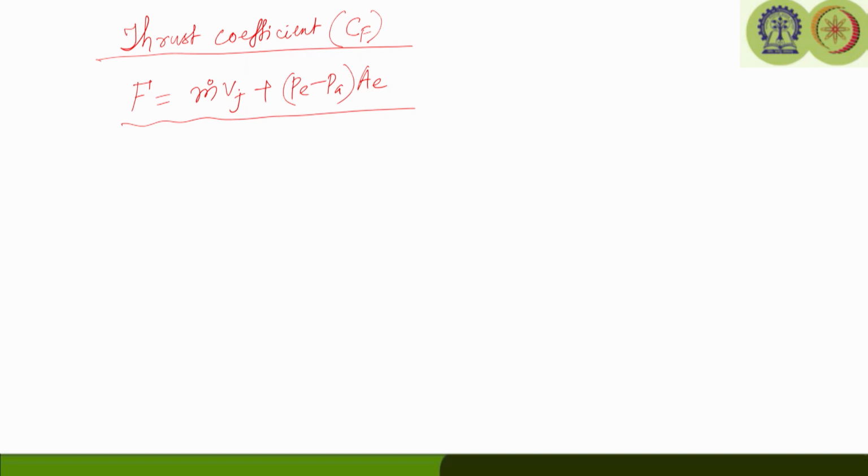Now, since the flow is supersonic, the exit pressure at the nozzle does not necessarily have to be always equal to the ambient pressure. It is not necessary that P will always be equal to Pa, which we already learned from our previous courses like high speed aerodynamics or gas dynamics, where we have seen that P may not be equal to Pa. In a case where P is less than Pa, we consider this case as an over expanded nozzle. Of course, this will have some issue with flow separation,